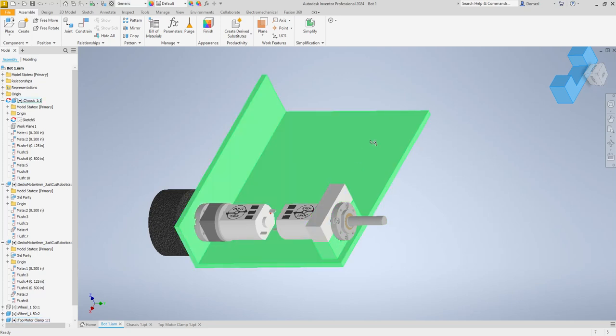Those two clamps are there. How are we holding those two clamps together? Right now, are we? No. How could we hold those two clamps together so they actually stay in place? A number of right answers. Screws, probably the easiest answer to do. We could glue it, but then we'd never get it back out. We could use zip ties, put a channel in there and zip tie it. Probably a bunch of different ways we could do it. So if we're going to screw in here, we can then start creating some holes to put those screws in.